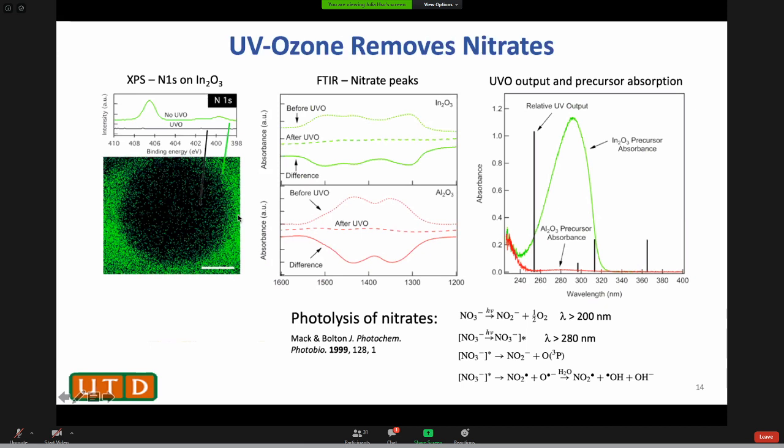So we can make these transistors. However, for each layer, this did the aluminum layer, actually we did 2 layers for the gate dielectric. So that's 80 minutes of UV-ozone and annealing. And the indium oxide takes 10 minutes, okay? So this is still minutes, a long time of annealing. So that brings me to the next topic. How can we do this for large area, and how do we do it fast?